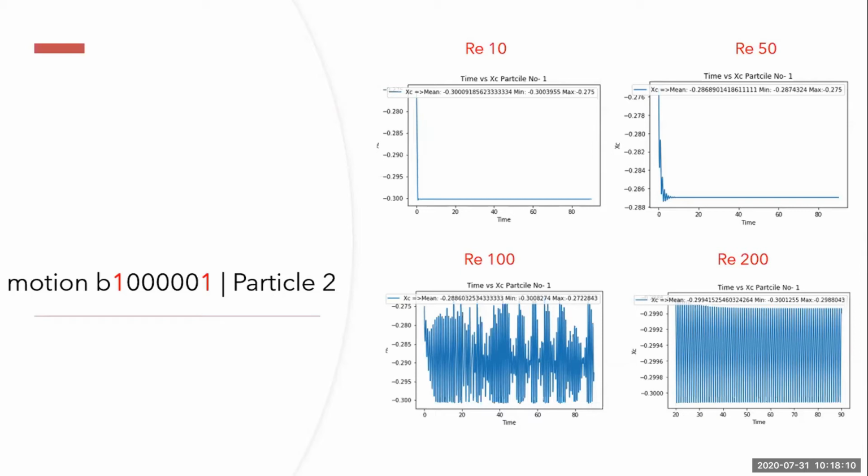And in Reynolds number 100, there's a vast difference, where there's disturbance from the beginning and all throughout the simulation. This unstableness is not even periodic, but chaotic, in the sense that it's moving to different positions at different times. And of course, we have Reynolds number 200, which is periodically moving. It's very similar to Reynolds 200 in 1D motion as well.